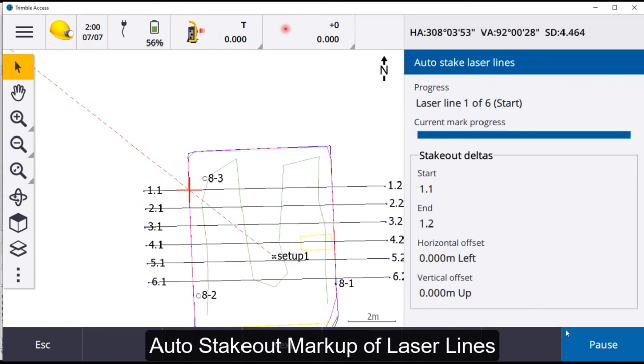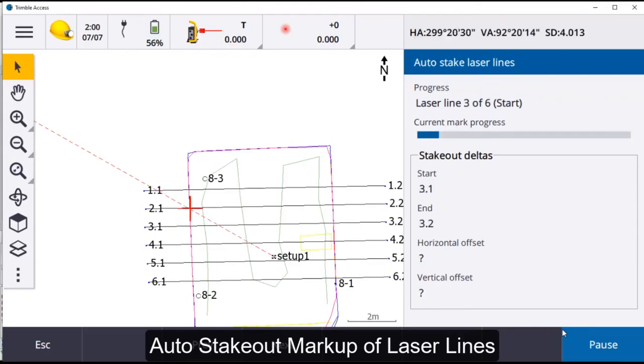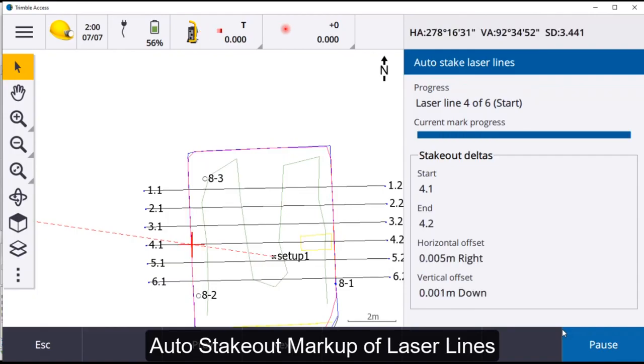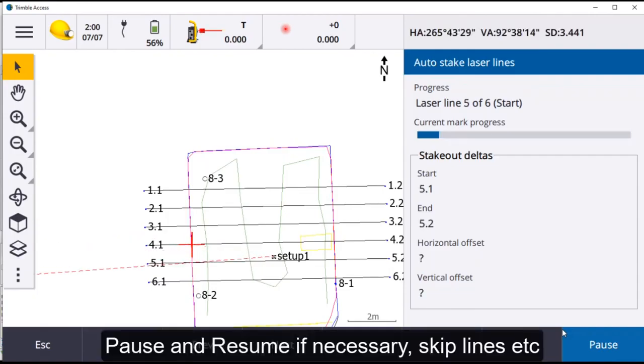Mark point. Marking point. And as it goes through that first section that we've selected, Mark point. When it reaches number 6, it'll cycle around and go back to the first point. And you can stop marking out. If you have, say, 100 rings in a panel and you know which ones you're going to be marking out, you can stop, select the ones that you want before you even begin setting out. So you don't have to skip past every point each time.